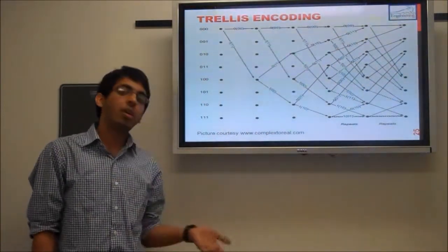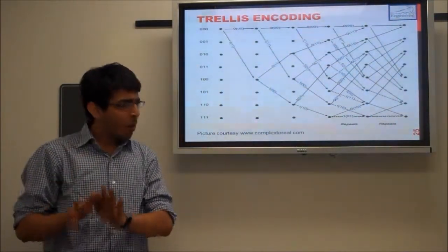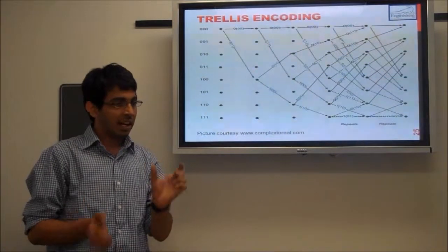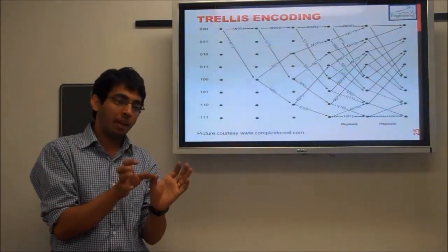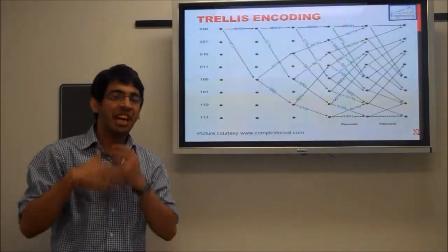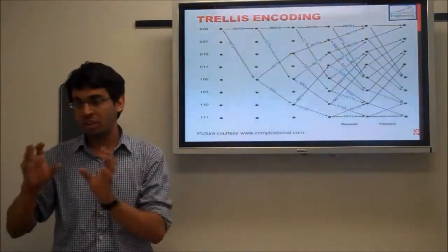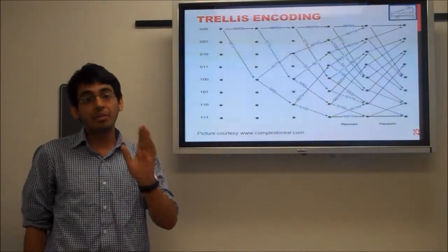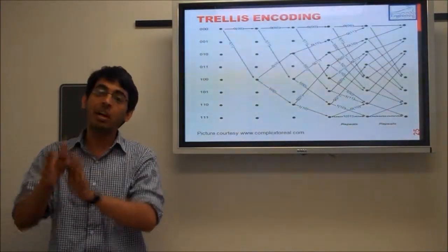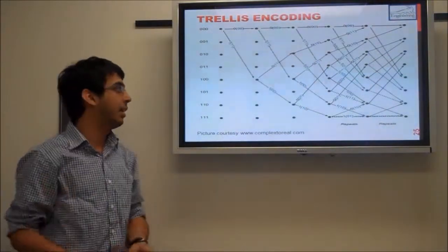Again, there is one point which I forgot to mention in the previous slide when I was discussing channel encoding. What typically happens in a channel encoding scenario is that you have a stream of inputs, and then you add redundancy to that stream, right? But then how do you gain? How do you get the channel gain out of it? You're adding redundancy, which means that you're consuming more bandwidth and more resources. But the gain here comes from the bit energy per symbol. So the energy per bit or the energy per symbol gets reduced when you have the error encoding in place. So this is how we get the channel gain.